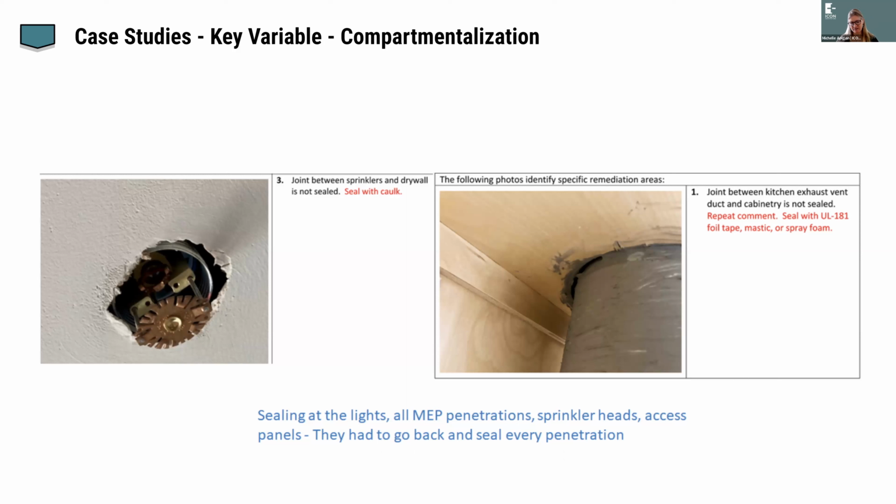In some of the projects I've got under construction right now, where we're doing, to Mark's point, early blower door testing to try to find the big issues. Let's not worry about the number, but where is air moving and why? Because we can design it with the best of intentions, but it ultimately relies on execution. So working with the builder, having them on early is fabulous, because this is a performance focus, not always prescriptive, and there's lots of ways to get there.